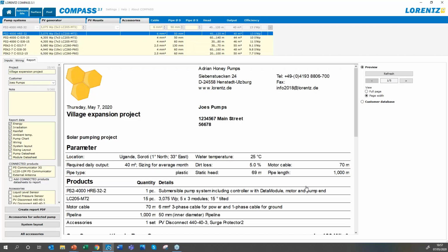So there's actually 3 different questions which I'll try and group together here, which talks about how we can look at maximum flow rates, for instance. So of course, if we look at the real world, then many boreholes actually have a safe yield or a performance that they're capable of doing. So a borehole should have a pumping report.